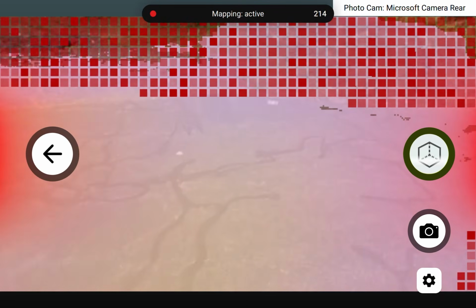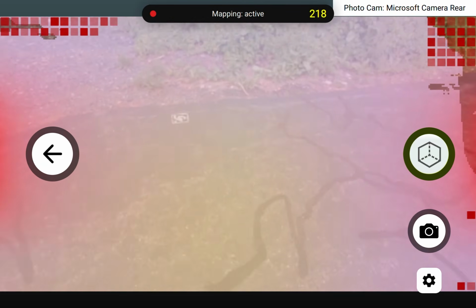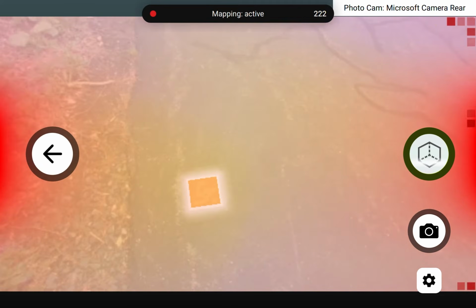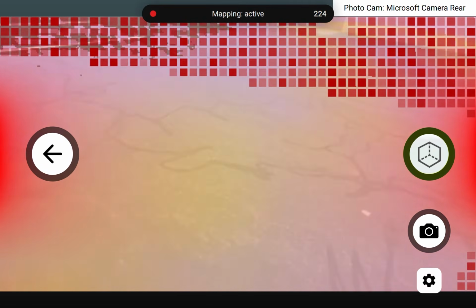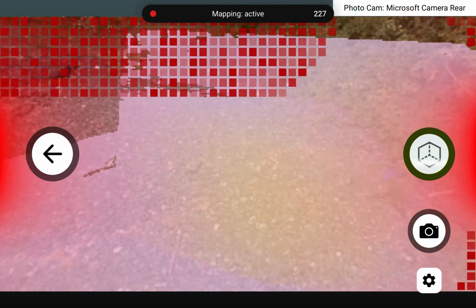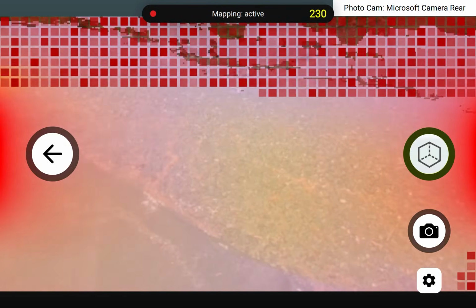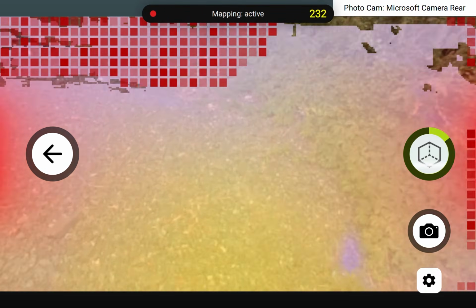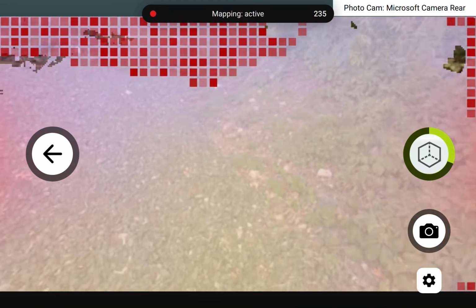If and when you do lose tracking from a challenging area like this, or simply because you tripped or somebody walked through your scan, don't stress. Know that Scan3D cut off capture to prevent you from getting any inaccurate data, and all you have to do is slowly back up to an area you were just scanning from and capture some good green data for it to relocalize and allow you to continue from where you left off.